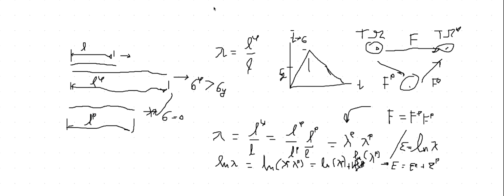So with this approach with the principal directions, it's very convenient. You take the geometrical nonlinear effect by computing the principal directions and then defining your strain energy in terms of the logarithmic strains. You can then recover what you've done in the small strain setting. The only difference is that you adapt your computation to the principal directions as opposed to the, let's say, small strain setting, where you typically do it in physical coordinates. But there's really no big deal in adapting those things to a special choice of coordinate system once you do it. And that's actually how you can do this large deformation elastoplasticity in a very clean way. So this is kind of the idea in a nutshell.